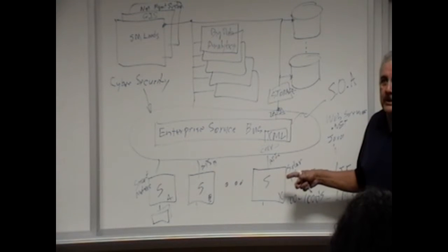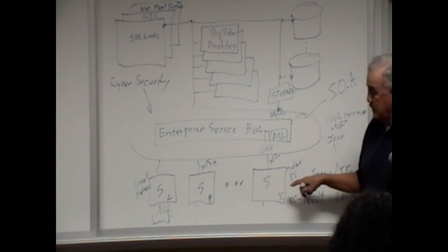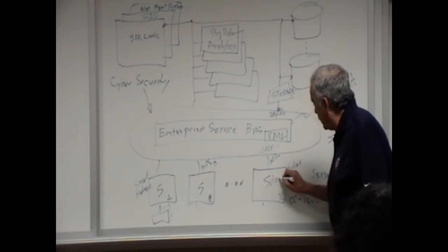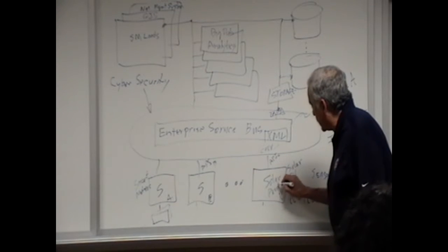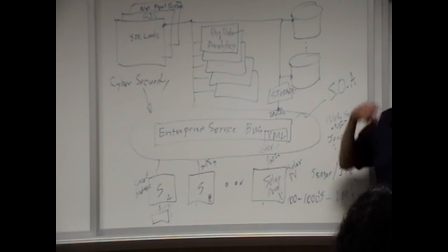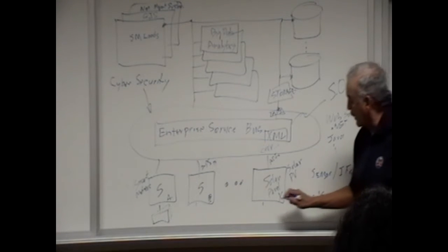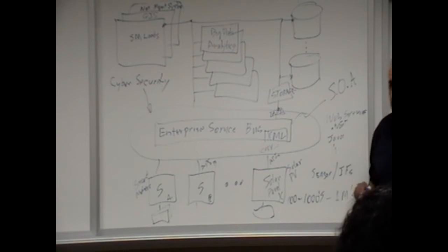If it's in series with all the rest of the panels, then you may have an outage. So this panel is not producing DC energy, it's not getting converted to AC energy, and the power that it's providing to the building is not available.